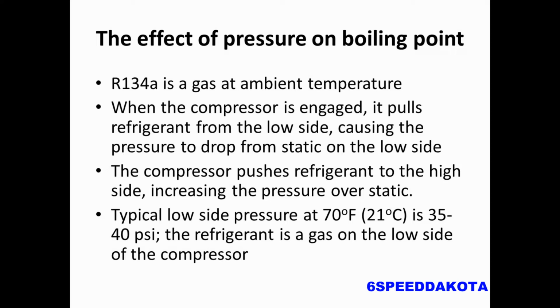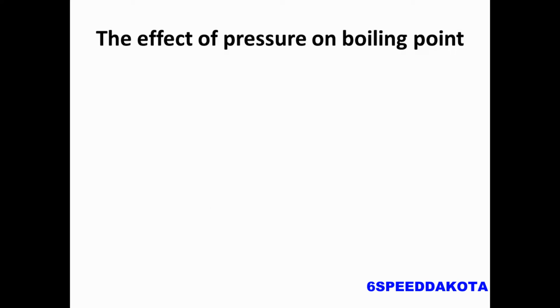Which means that the refrigerant is definitely going to be a gas on the low side of the system, if the refrigerant is usually a gas at a static pressure. So one thing you have to remember with this is as the temperature changes, so will your high and low side pressures and your static pressure, because as the system heats up, refrigerant is going to want to expand. Since the system is closed and sealed, the pressure will go up. So that's why I'm giving you the ambient temperature in these examples.